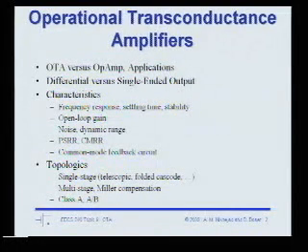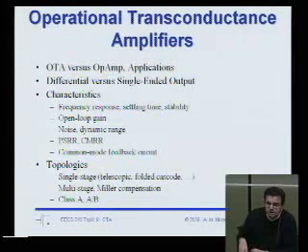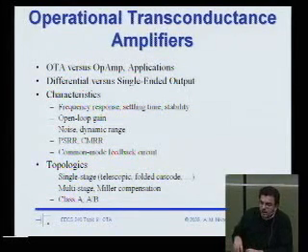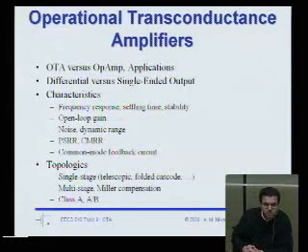The next thing we'd like to do, and hopefully by the end of this lecture, is to compare differential operation with single-ended operation and convince you that differential has a lot of benefits. And so if you ever have to decide between differential and single-ended, and the power penalty is not an issue, you should definitely go to differential. And then what we're going to do in the next several lectures is to analyze different OTA topologies. And we'll start out extremely simple. We'll start out with a common source OTA, and then build up into complexity and talk about different kinds of OTAs.